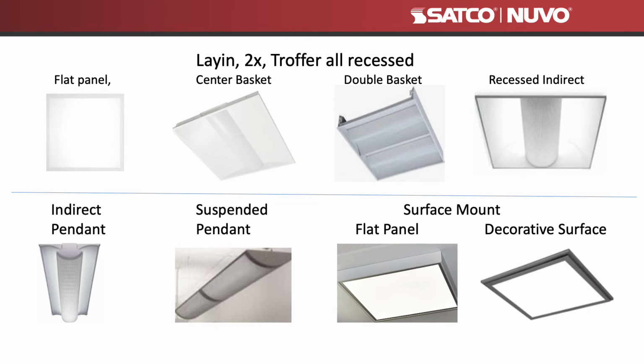Popular type for general lighting, talked about flat panel for lay-in ceilings. Then the next one, we have a center basket with one lens where the light emanates from that one center basket. Some people prefer a double basket, which gives a different look and feel and a different beam spread. And on the top right, an interesting fixture. It's a lay-in fixture or recessed fixture, but it also provides indirect light. It does that by having a basket where the light doesn't come out the front, but is reflected off the back. In pendants, we have indirect pendants, we have direct-indirect pendants.